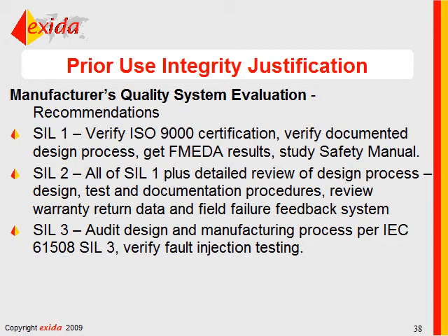I got a call from an integrator down in the Gulf Coast area of the United States, and he had just opened up the safety manual of a PLC that he had purchased. And he called up and said, "What does this mean?" and read the passage. And I said, "Well, that means you're going to have to use duplicate input modules, and you're going to have to program your own comparison." And he goes, "Oh my God, I don't have room for that.